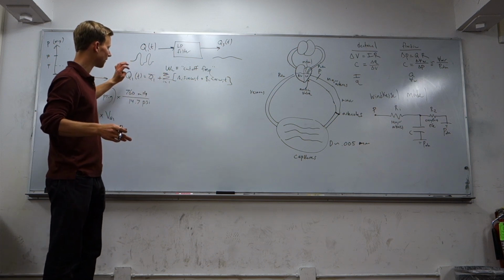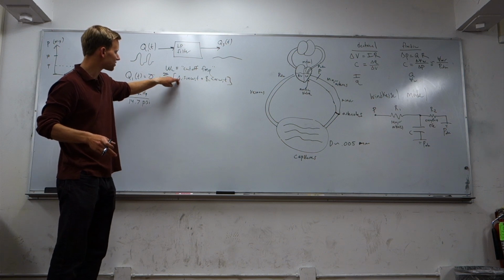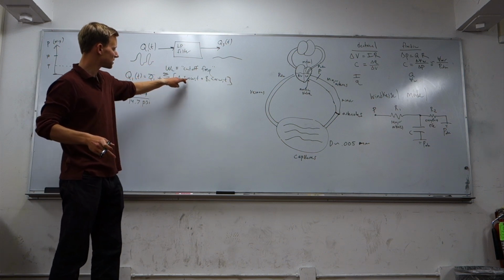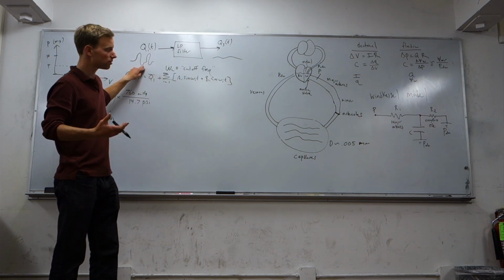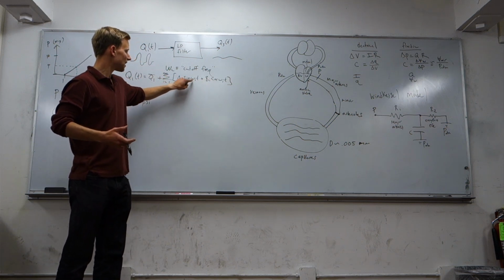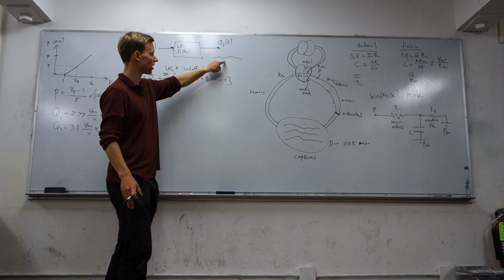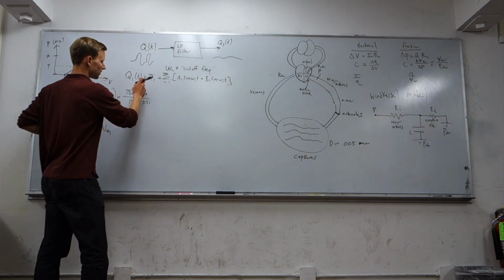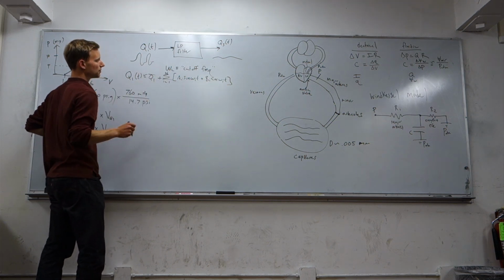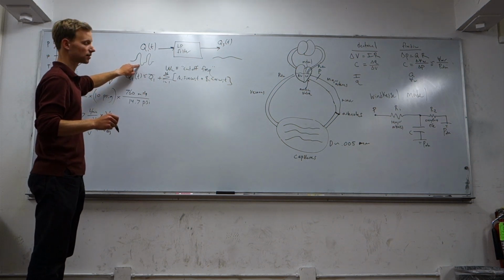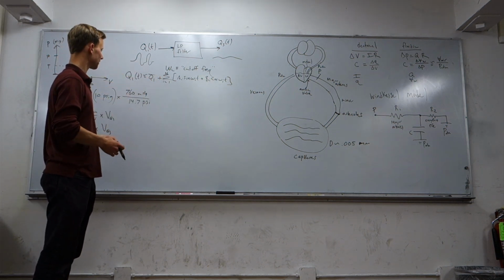It's called the Fourier transform. And then we can understand how much of our signal has certain frequencies involved. So this signal is composed of certain omega i's, and any omega i's that are bigger than omega c get cut off, and we're left with our output signal. Now, of course, for engineering, we can't use an infinite sum here, so we'll make this just a big number and make this approximate. So we won't be able to reconstruct this signal exactly with sines and cosines, but it will be very close. We'll see.